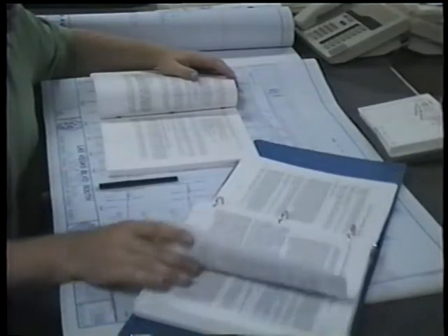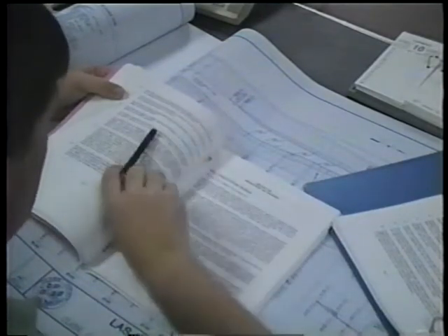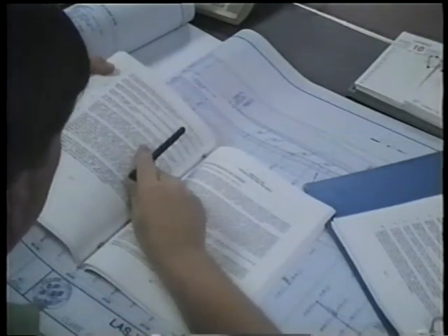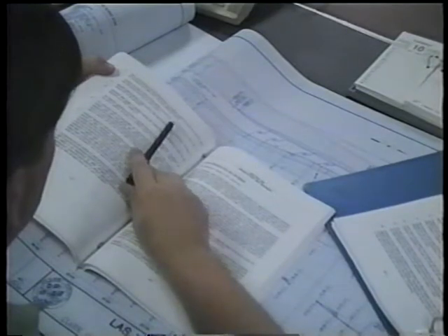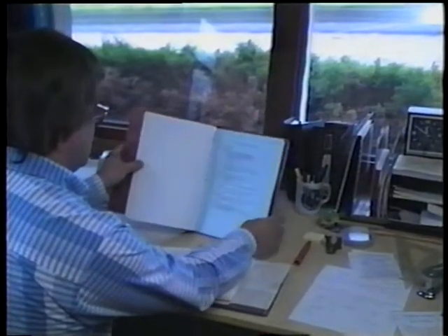First, as with any project, review the contract documents. This includes your agency's bid specifications, including amendments, any special provisions, the appropriate sections of the construction manual, and the traffic control plan. Paving details can vary significantly from one job to the next, especially for traffic control. The traffic control plan identifies the types of signs and devices necessary, as well as their placement. So always study it carefully.